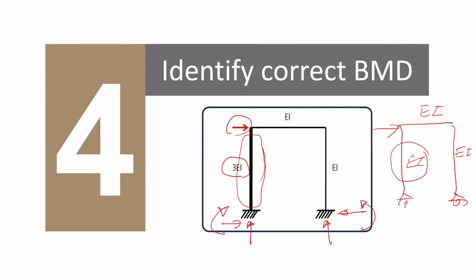But here, because the left column is stiffer as compared to other columns, it will attract more forces, and this is an indeterminate structure. So remember, there's one caveat: the structures are democratic if they are indeterminate structures, and most buildings and bridges you find in reality will be indeterminate structures. It means that there will be extra elements than needed to provide a level of redundancy in the structure, so that if one member fails, others take over and modify the load path.